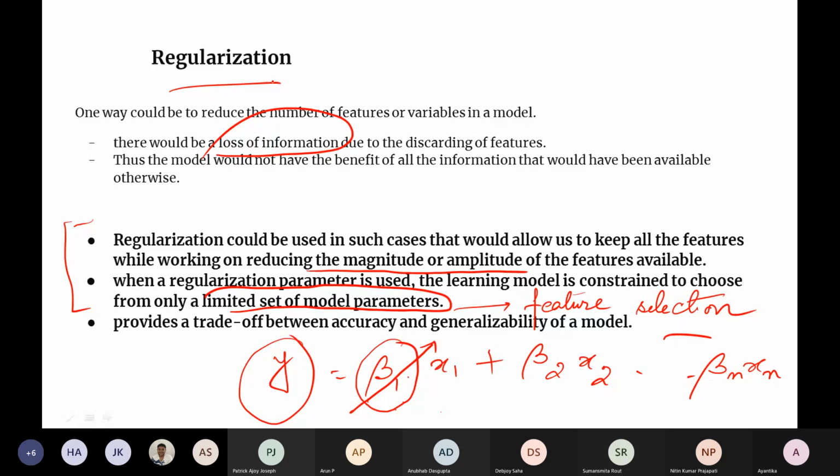in your general application always. But when you are coming to this embedded ML scenario, regularization is also one key operation that you have to consider, because with regularization or proper feature selection, you can check if you can reduce more, throw out some more parameters, so that it will give you some advantage in terms of energy or memory access. So that's why we are discussing regularization here.